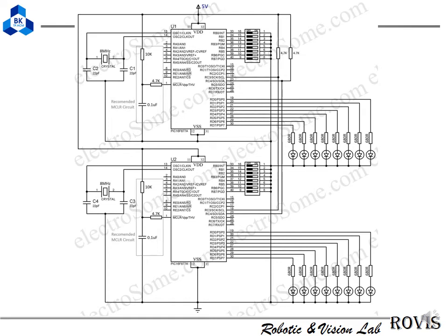And we go to another example. The example is the transmission between two PICs. One is the master and one is the slave. This will read the status of port P, and then transmit the status of port B of the master to the slave, and then transmit the status of port B of the slave to port D of the master.